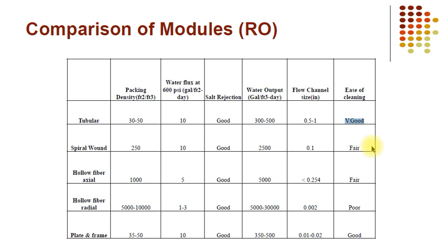And before the spiral wound module, we use a cartridge for removing particles, as well as a carbon cartridge for removing gases. So water should be pre-treated before going to the spiral wound module, otherwise your membrane will be destroyed very quickly.